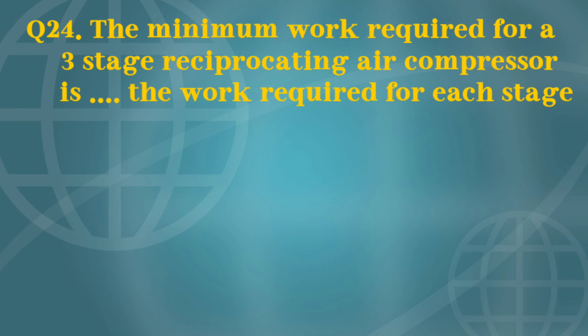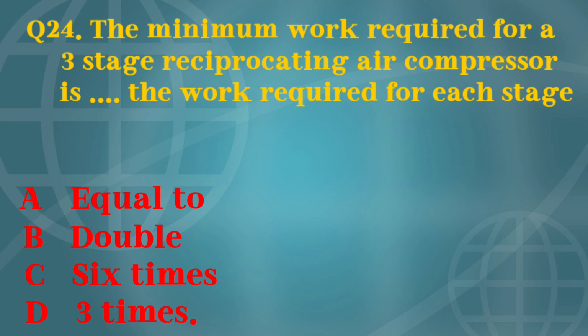Your question is, the minimum work required for a three-stage reciprocating air compressor is dash. The work required for each stage is. Your options are equal to, double, 6 times and 3 times. Your right answer is 3 times.